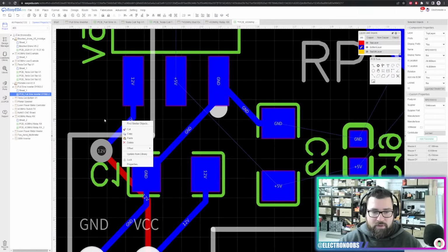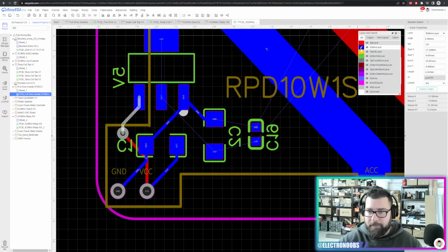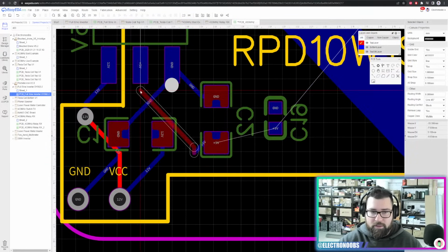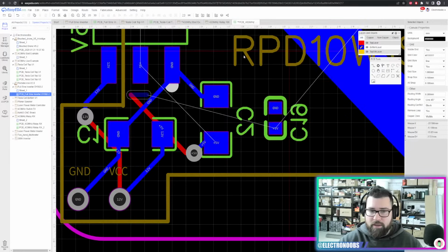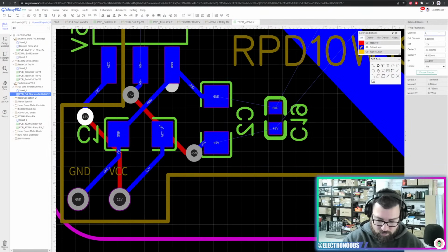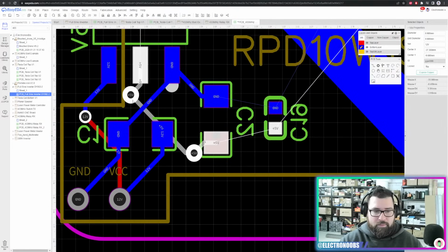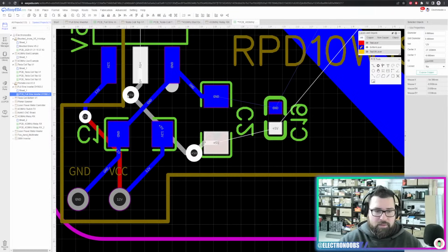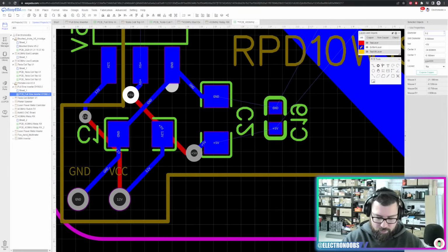Once again, I'm doing this very fast. This once again will go like this. On the top side, we add a via like this. These vias now are too big. 0.9, 0.6, 0.4 better. Yes. 0.9 and 0.4.